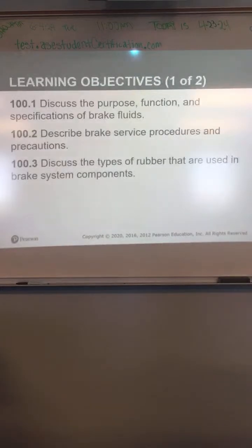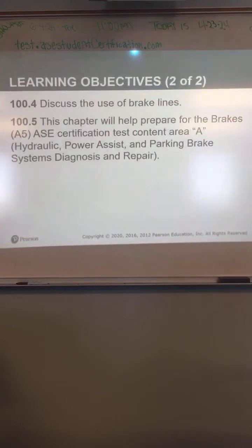Okay, let's go through the brake fluid and brake fluid lines. Purpose, function, and specific brake fluids. We're going to go through the different types of brake fluids, brake service procedures, precautions, and types of rubber that's used in the brake system components. Obviously, the brake fluid can't have a negative effect on the rubber seals in the brake system. Otherwise, you'd have problems with the brakes. Sometimes people put the wrong brake fluid in the master cylinder, which contaminates the whole system. Everything at that point has to be replaced, okay?